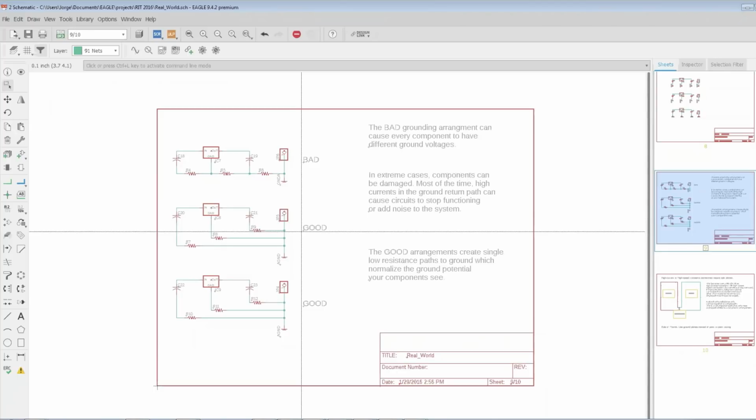And if you have a ground plane, okay, the current that flows through the ground plane doesn't just uniformly distribute. In a future webinar, we're going to see that in order to minimize impedance, because the signal is going to flow through the minimum impedance. It wants to minimize it. And that occurs when it's right below the signal path or right next to it, as close as possible to it. That's when you get minimum impedance. Okay, and that's how currents want to flow in a ground plane. They don't just distribute evenly, like if you were throwing a drop of water into a bucket. Okay, it's actually picking a specific section of the ground plane to travel through.